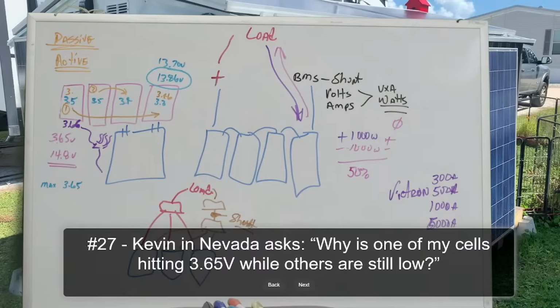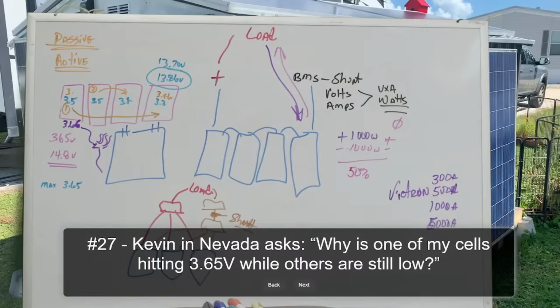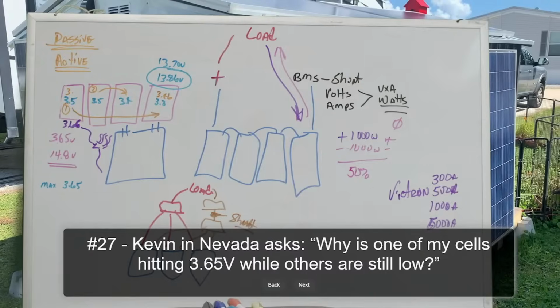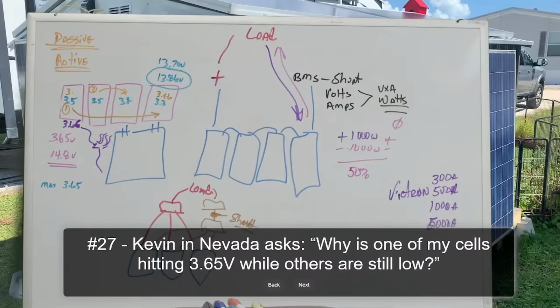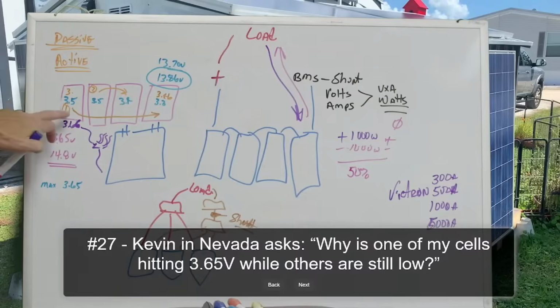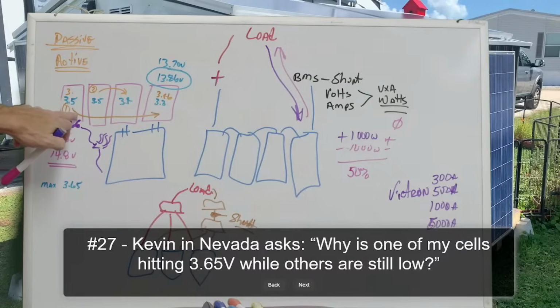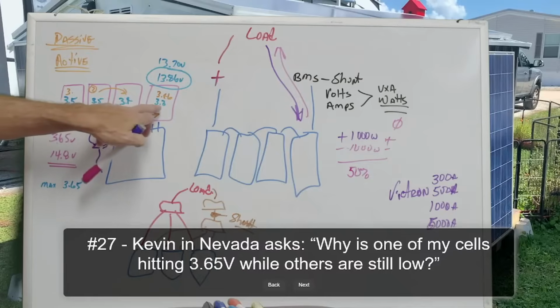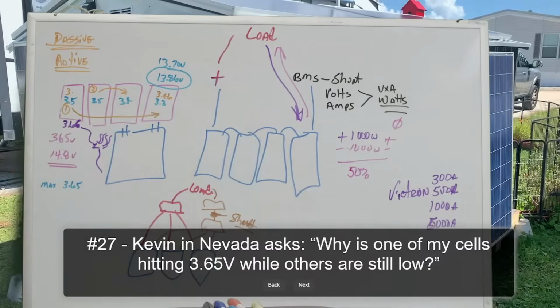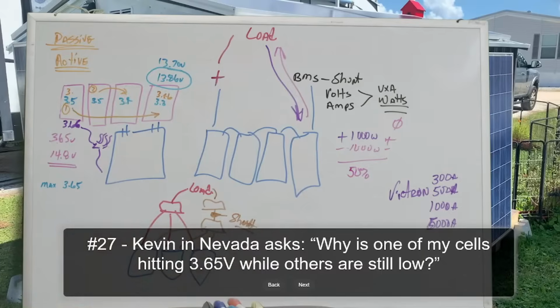This is a real important aspect of state of charge being inaccurate, because you can easily get a group of 3 or 4 or 5 cells in a 16 cell battery that are up in the 3.6, 3.65 range, and then several that are down in the 3.3 range, and see a huge swing in the voltage of the battery.